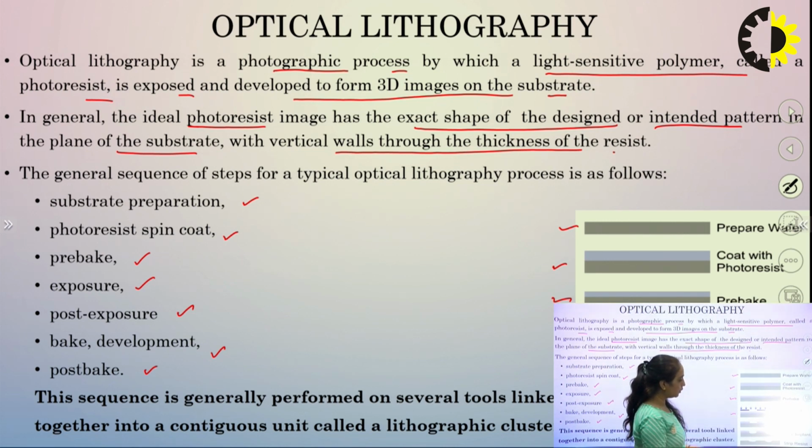Under the development solution, the portion that is not exposed to UV light will remain hard and the rest will be soft. During development, we are going to have this kind of structure, and during etching some portion is removed, the oxide under it is removed, and then we strip the PR. The function of the PR is done, so we can remove the PR in the last step.